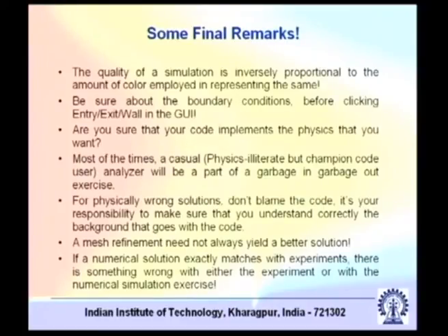So you have to be very careful whether the boundary condition that you are implementing represents the right physics. Not only the boundary condition, in general, are you sure that your code implements the physics that you want? This is very important because all problems do not have the same physics. Say you are interested to solve for a rarefied gas dynamics problem.